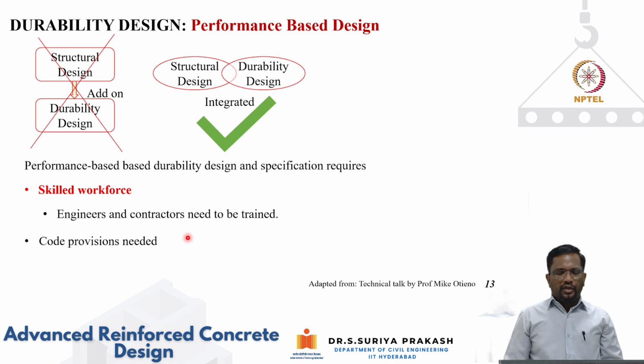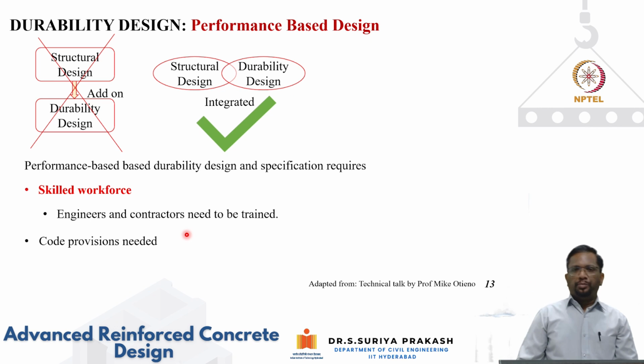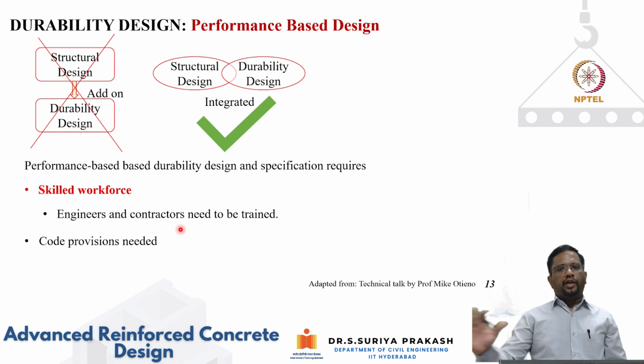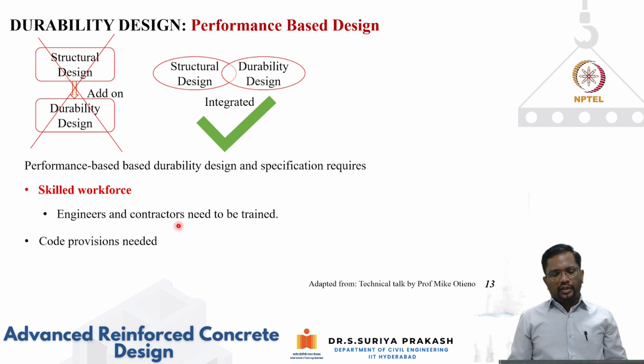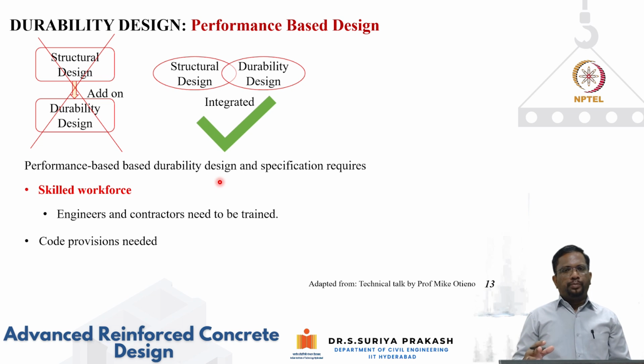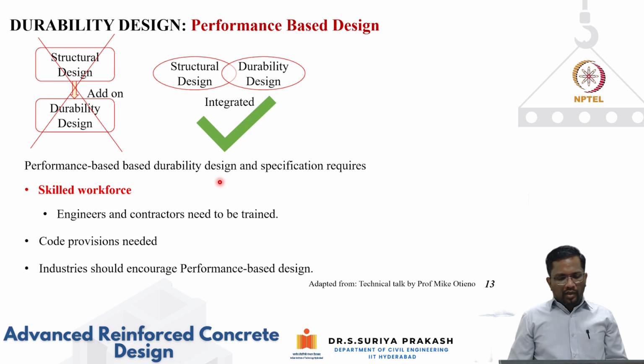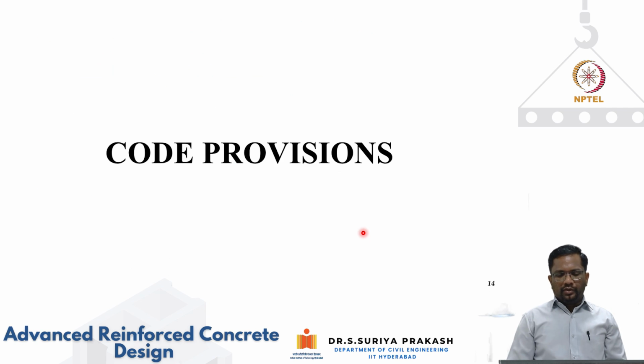In fact, I am told that IS 456 also is undergoing major revision, and we are in a way moving towards performance based durability design. So a lot of these aspects that we have discussed will be included in this revised IS 456, where you're not going to just use the prescriptions that are followed in the code, and the code is also going to give you a lot of options for design engineers to choose a mix design that will satisfy specific durability design requirements. And the industry also should encourage performance based design. So, more acceptability from the industry is also important.